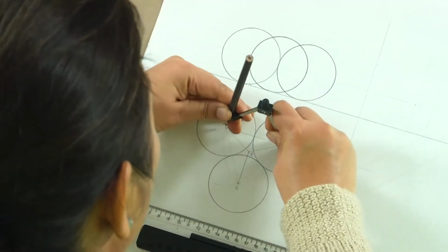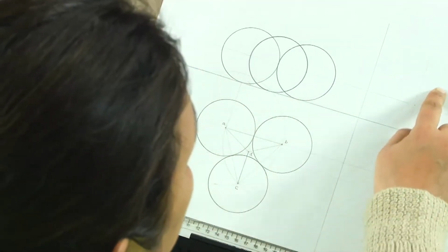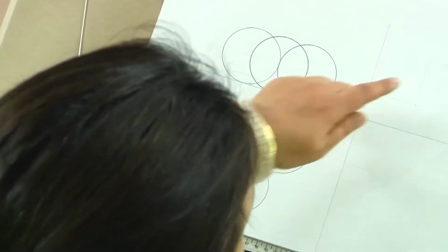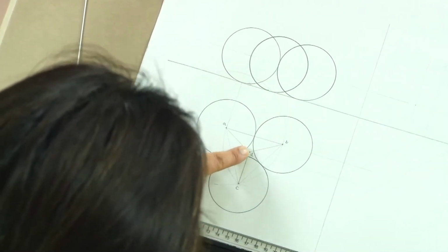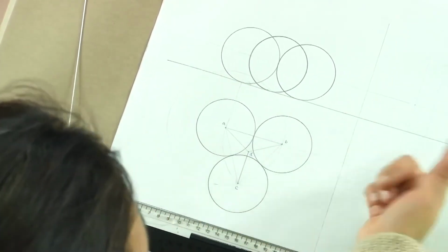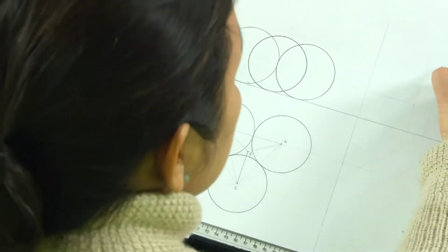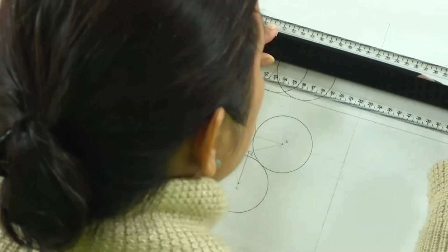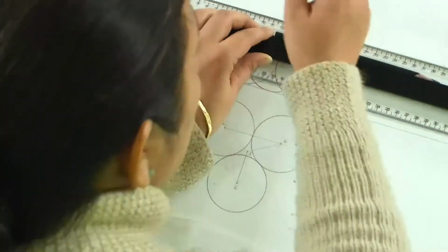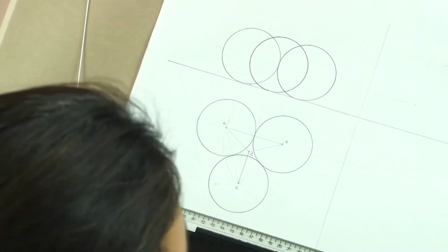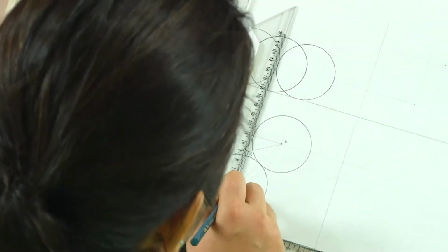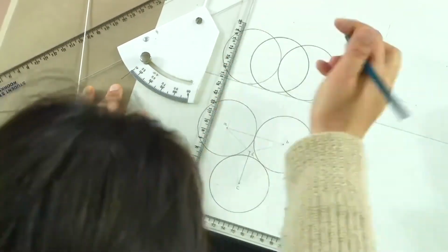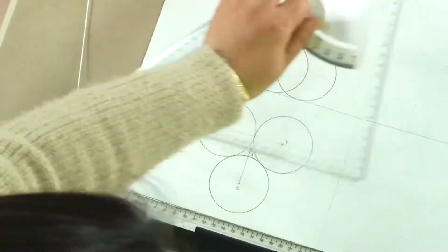So what we will now do is, we know that this D is lying on this vertical line. So we know the distance between C and D, which is what this distance is, because this line C and D is parallel to the side plane. So we have now got this point D in height, and we will not make spheres here, we will just take it to the VP, and from here we know that D is going to lie here. So if you match the orthographic projections, this is the point D.